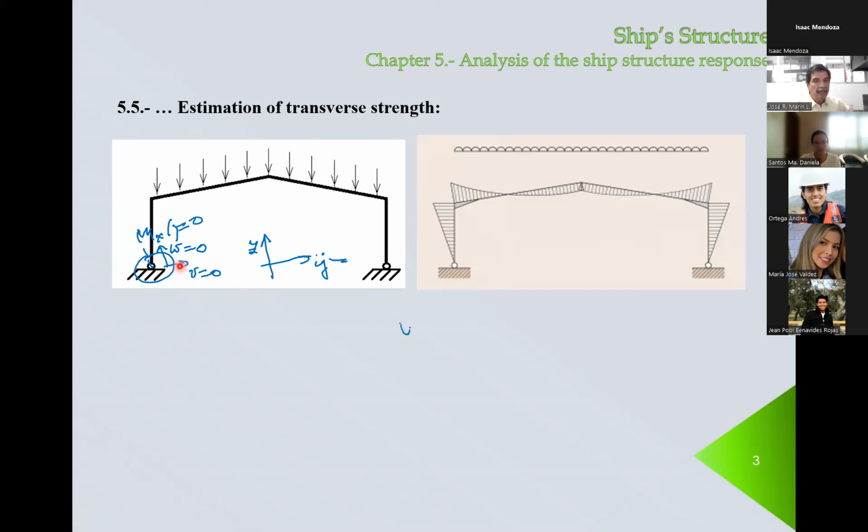So there's going to be a shear force in the y direction in this point. If you have a certain shear force here, and there is no loading, dM/dx is equal to minus V. So since V is a constant, then the bending moment changes linearly. And that's what we're seeing here.